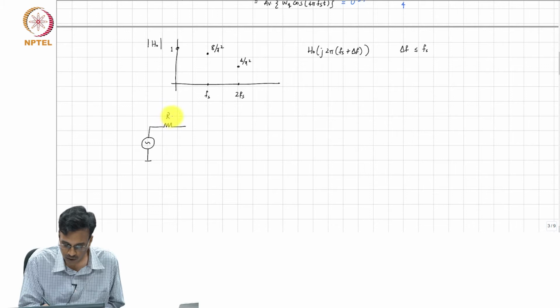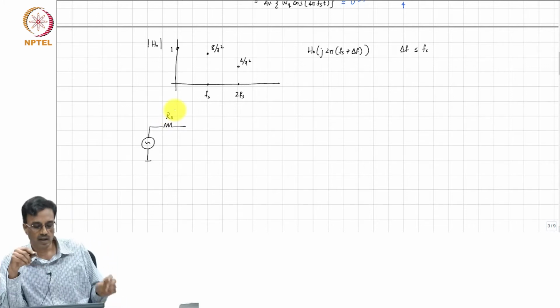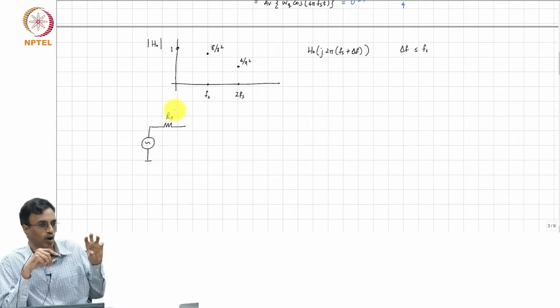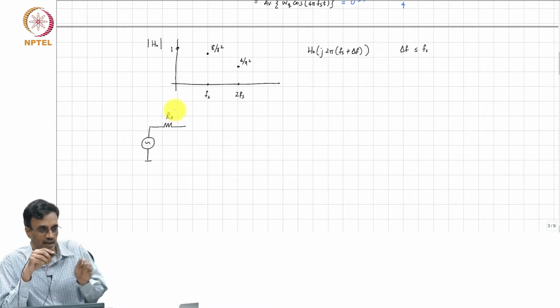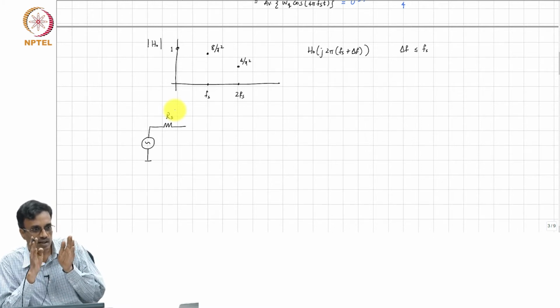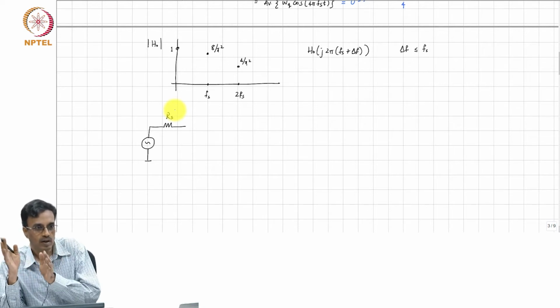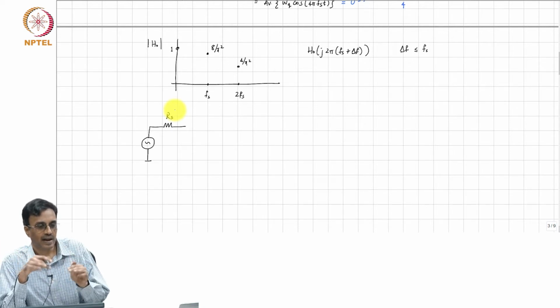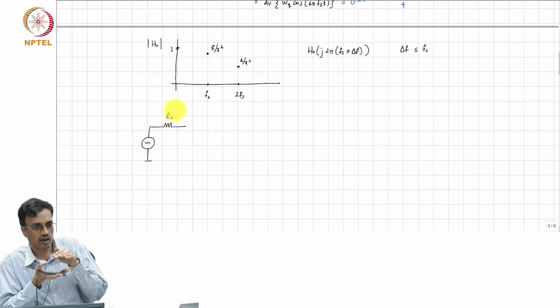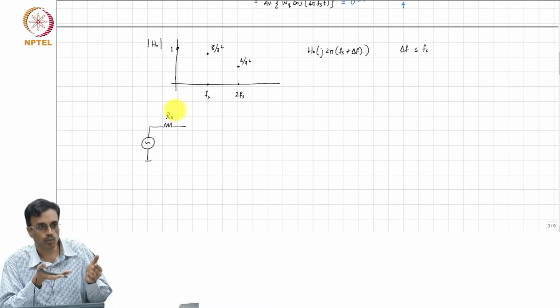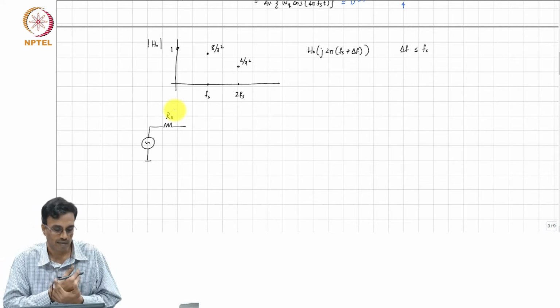and intuition about. We already have seen that if the input frequency is not exactly Fs, then each capacitor is going to see different sections of the input waveform over that quarter period, and therefore, the magnitude of the voltage across the capacitor is going to be much smaller than what it would have been if the input is an integral multiple of Fs, right.